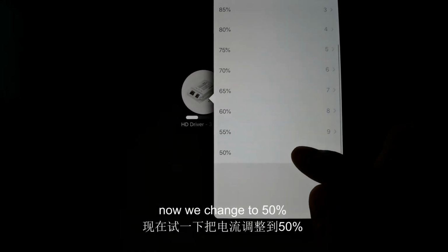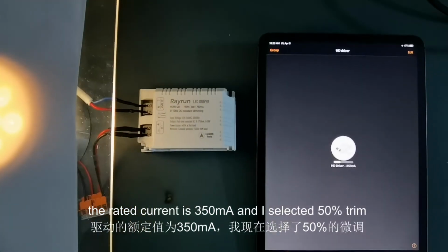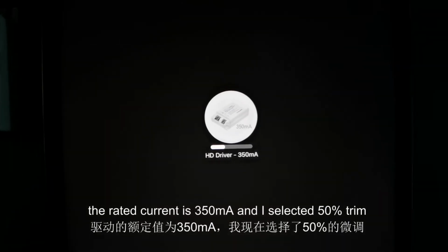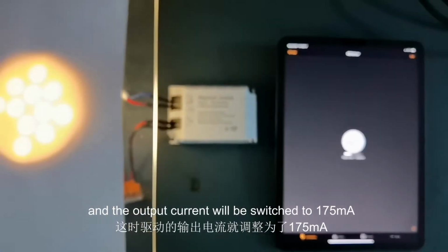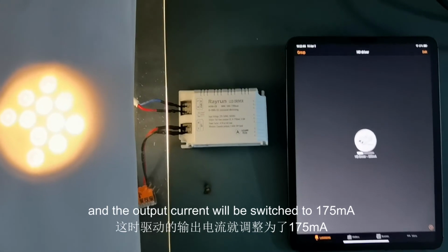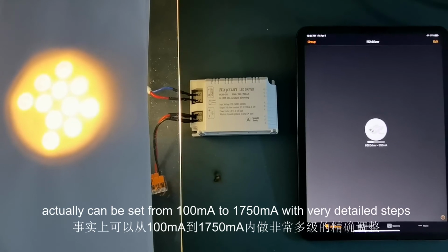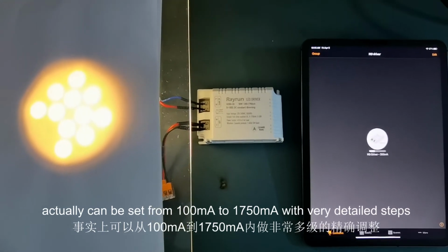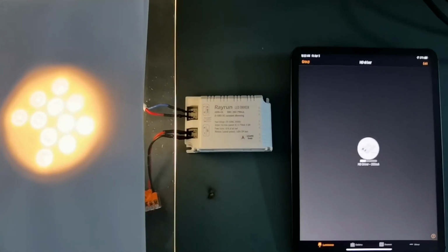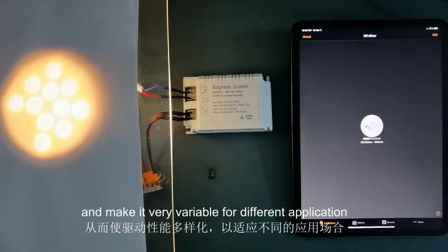Now we change to 50%. The rated current of the driver is 350, and I selected 50% current trim, so the output current will be switched to 175 milliamperes. With this feature, the driver's output current can actually be set from 100 milliamperes to 1750 milliamperes with very detailed steps, making it very reliable for different applications.